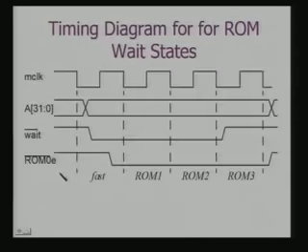But now, let us look at this timing diagram. Effectively, this wait goes low here, and this ROM enable has to be active for this time period, because these are the 4 cycles which are required for the access. So, this is now the timing diagram that would be there when I am using a ROM which requires 4 clock cycles for an access.